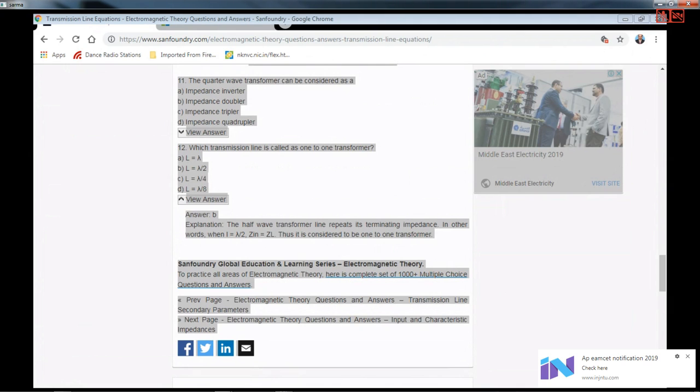So in terms of this capital gamma, whatever we have just now defined, the voltage and current expressions are shown. The voltage and current expressions are given in terms of the load coordinates, Z prime. So IL by 2 (ZL plus Z naught) e power gamma Z prime times (1 plus capital gamma e power minus 2 gamma Z prime).